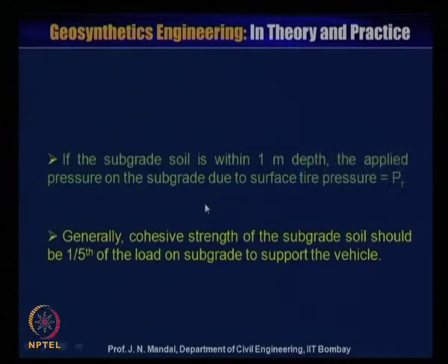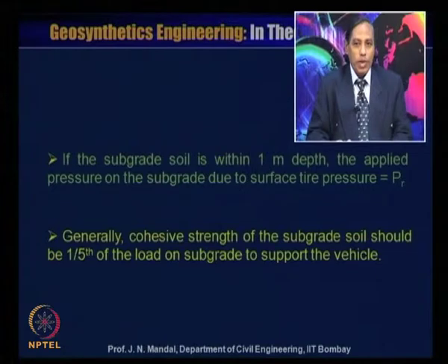So if the subgrade soil is within 1 meter depth, the applied pressure on the subgrade is due to the surface tire pressure PR. Generally, the cohesive strength of the subgrade soil should be 1/5 of the load on the subgrade to support the vehicle.